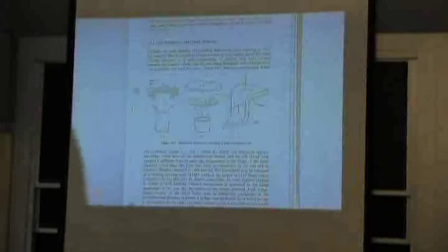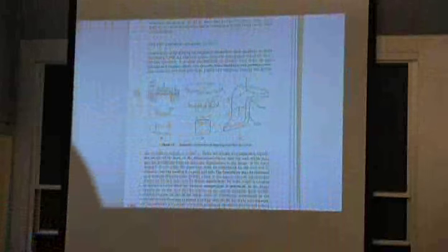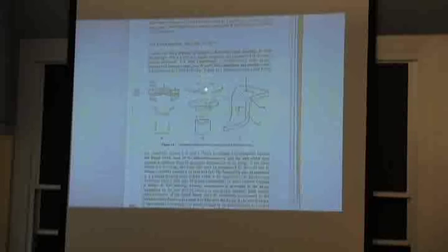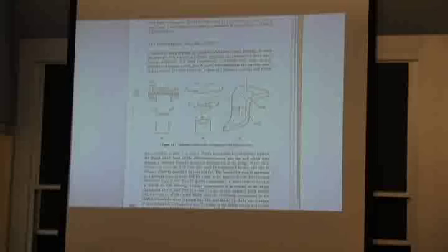So now let's start talking about sheet metal forming. And this is, how do you draw a cup? Okay, I keep using these cups, and I won't have to keep bringing them once we get into sheet metal forming. So I start out with a blank. I start with a sheet and I punch out a blank and I draw it with a punch and a die, and when it's being drawn, it sucks in the sides unless I clamp it and hold it tight, and I'll show you something about that later. It sucks in the sides and I end up with a cup that looks like this.